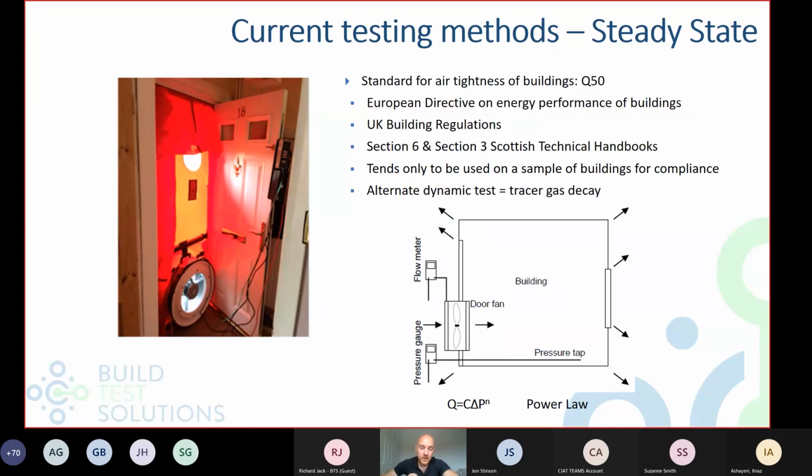So quite high airflow exchange between inside and out makes it necessary to record the conditions externally in terms of barometric pressure and temperatures inside and out. And you're taking a series of readings across a range of pressures. And yeah, we're taking a pressure tapping both inside and out. And you plot that flow versus pressure difference to derive the air leakage at a given pressure level.